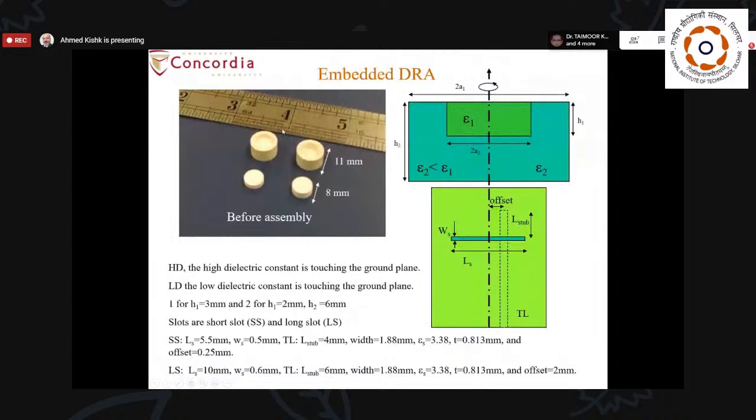So in order to avoid that, we made the lower dielectric constant a cup, and the other one is a disc that we can press inside. With just the friction type of contact between the two dielectrics, you have it exactly on the center, and you have no problem of adjusting them on top of each other.